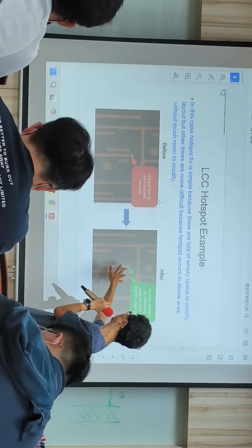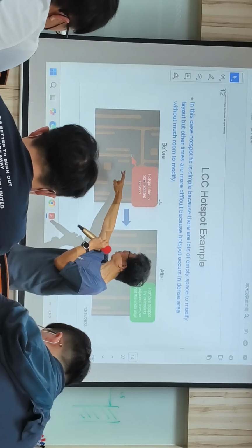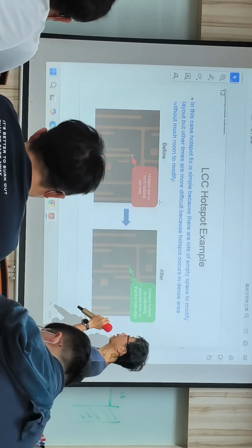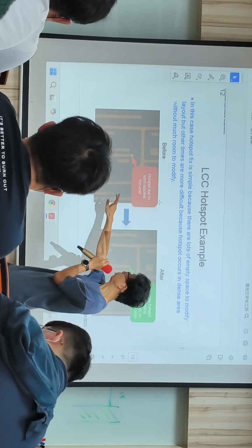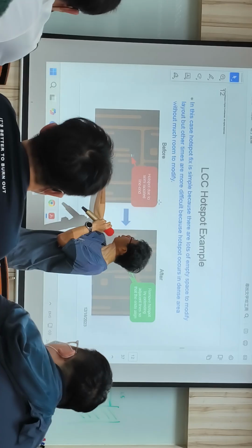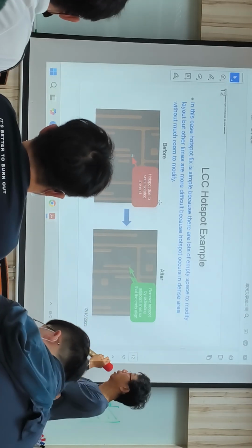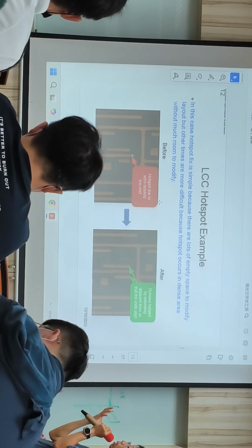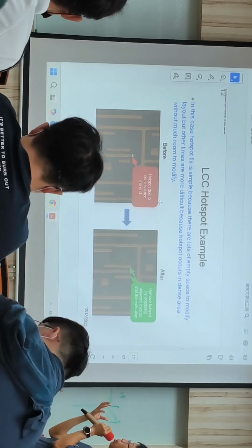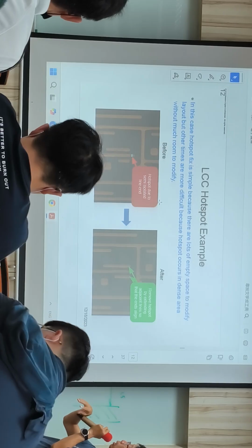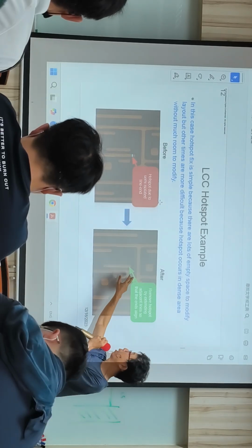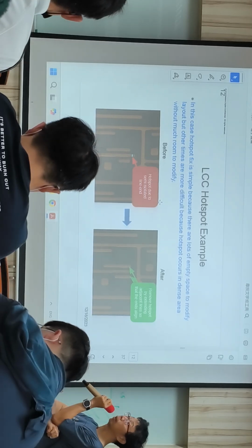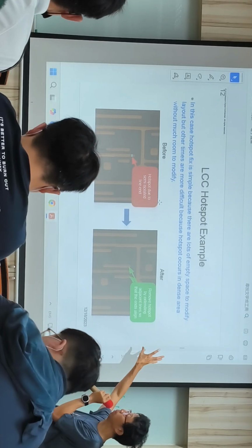One way to fix it is to make all this line longer, just parallel to that, and then this hotspot will be gone. So the blue area here is the so-called hotspot, and a design or layout engineer will come to the litho engineer and ask how to fix a hotspot before doing the tape-out. So as I mentioned,